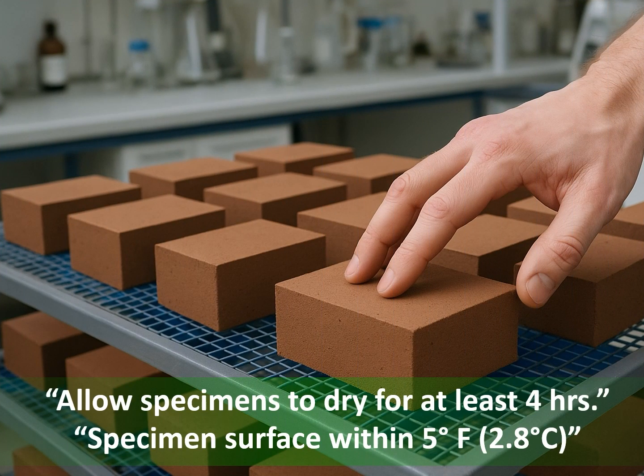Allow the specimens to sit for at least 4 hours and until the surface temperature is within 5 degrees Fahrenheit of the drying room temperature. Do not use specimens that are obviously warm to the touch for any tests that require dry units. The specimens shall remain in the room until the time of test.